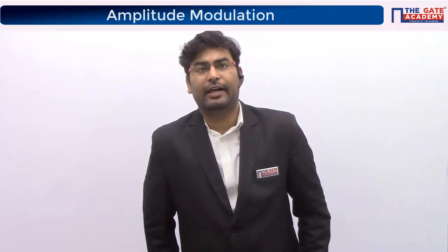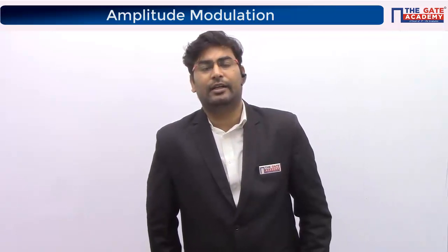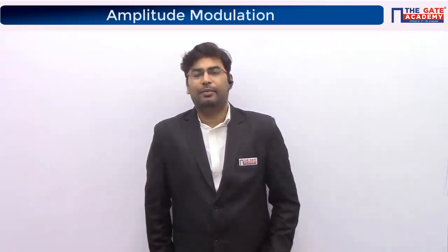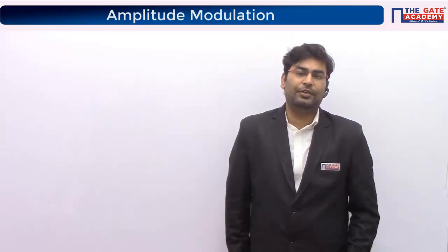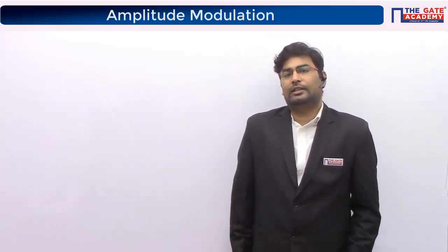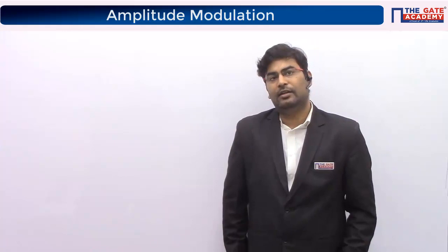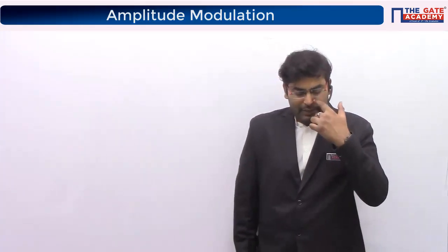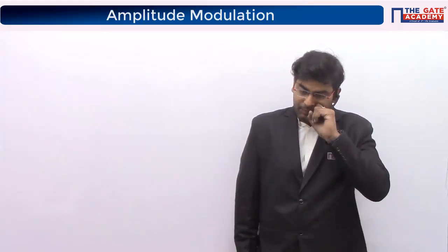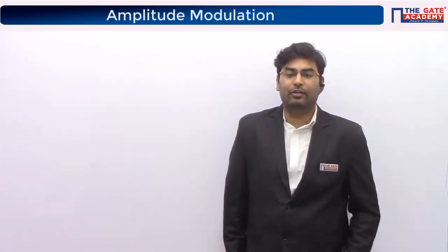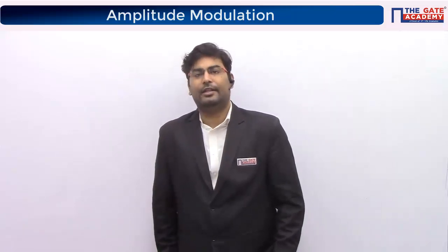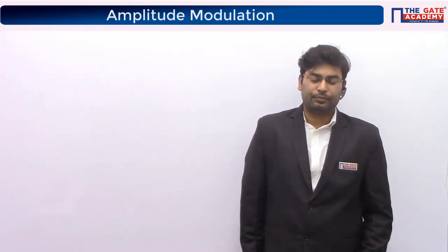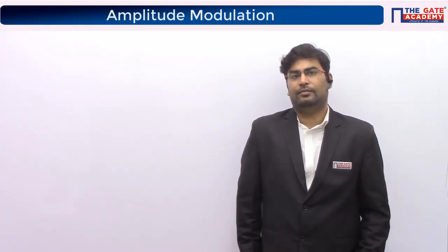Another question: the envelope started at 5, and what is that? Is it AC or anything? It's an AC signal only, but it's not only AC, it is a multiplication of one AC, which is the low frequency message signal, and another AC signal, which is the high frequency carrier signal. It started at 5 because when we took m(t), it started from 0. Then we added, I guess, 5 volts, so that 0 became 5 and minus 5 became minus 2. So it is AC only, embedded with the carrier signal.